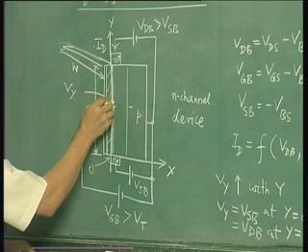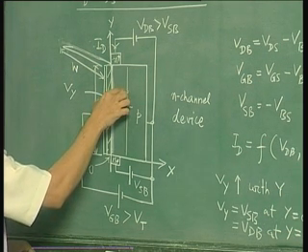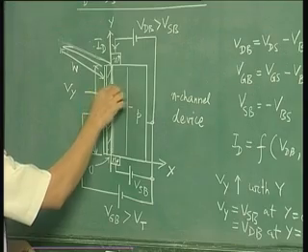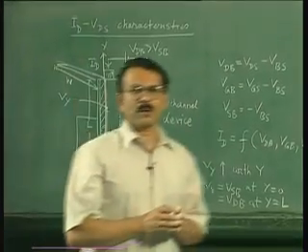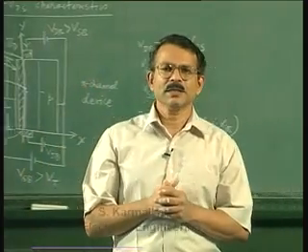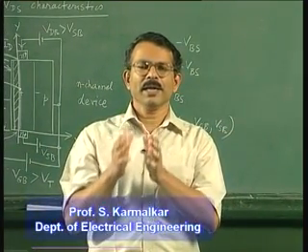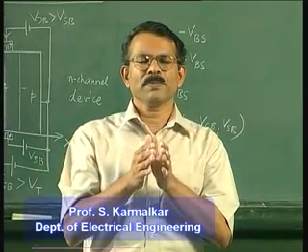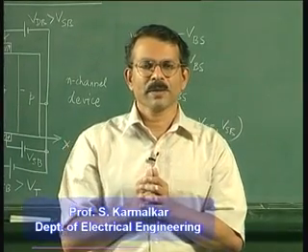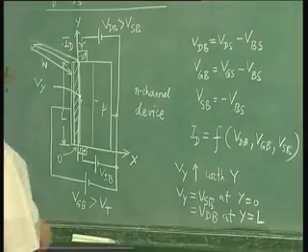Now if the voltage across the oxide reduces, obviously the total charge, that is inversion plus depletion charge in the substrate, will decrease. This follows from the parallel plate capacitor analogy. So charge on any plate or electrode depends on the potential drop over the oxide. We have discussed this in the context of MOS capacitor. We have also discussed this in the context of body effect.